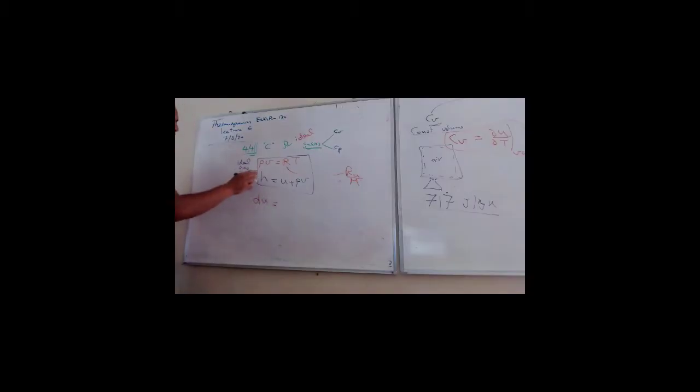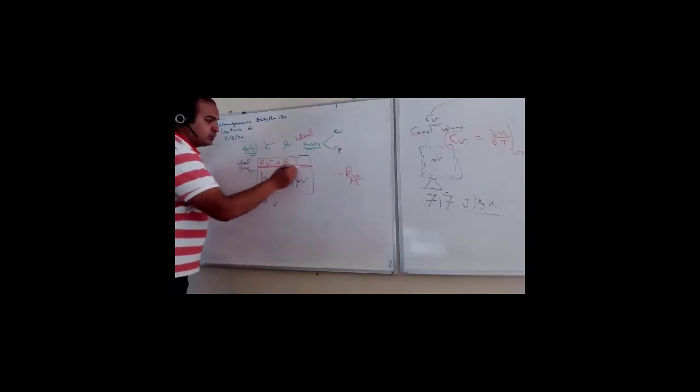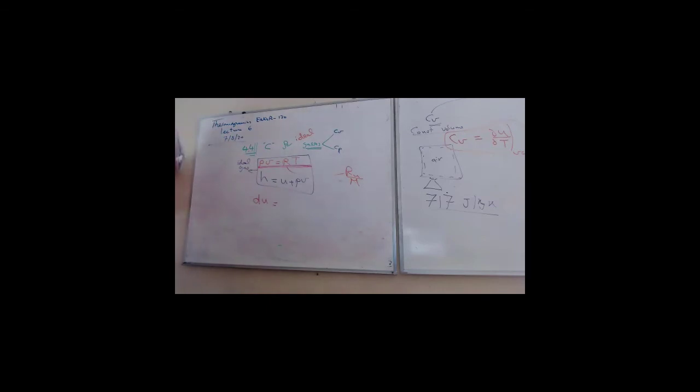So these are the two equations. The first one is very important for gases. I keep saying gases because I'm sure one of you will use it for a liquid, maybe a solid. I don't know how, but he will use it for something strange. PV equals RT only for gases and vapor, superheated vapor, like air, oxygen, even steam of water, but only when it's in the vapor phase, gas phase. H equals U plus PV is always correct.